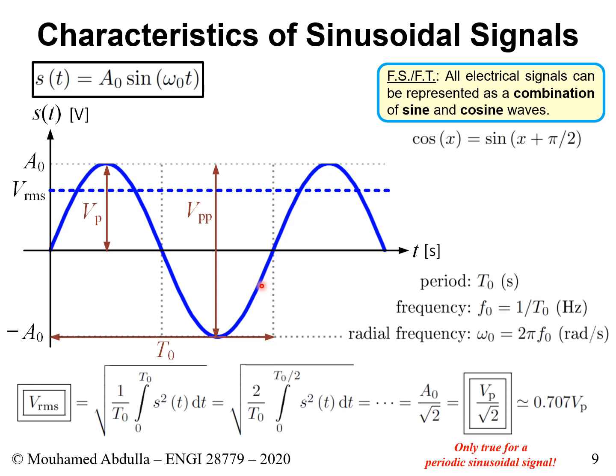In telecommunications, power is everything. Power tells us how the quality of a signal is. We will later on talk about SNR and SINR, and this is a metric for the quality of a signal. And therefore, when you measure these things called SNR and SINR, power is what you're looking for. Therefore, knowing the power is necessary. And without the RMS value of a signal, we will not be able to find the power.